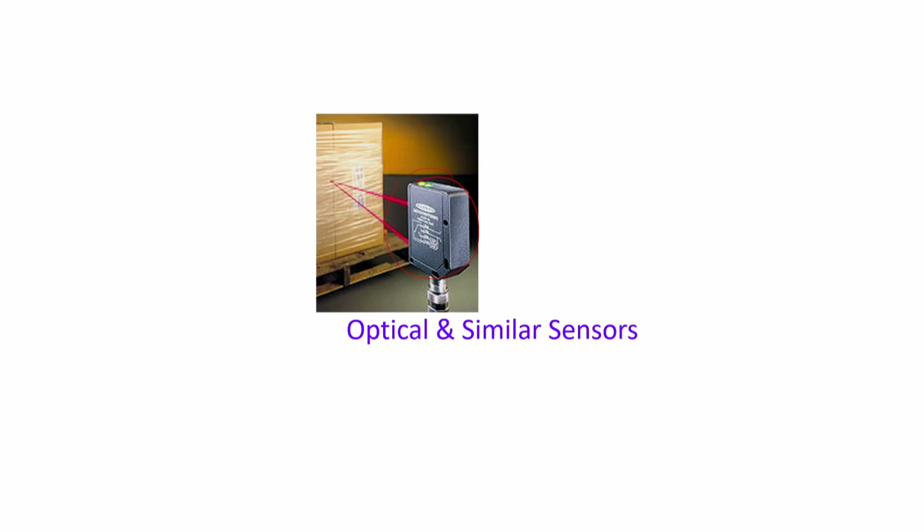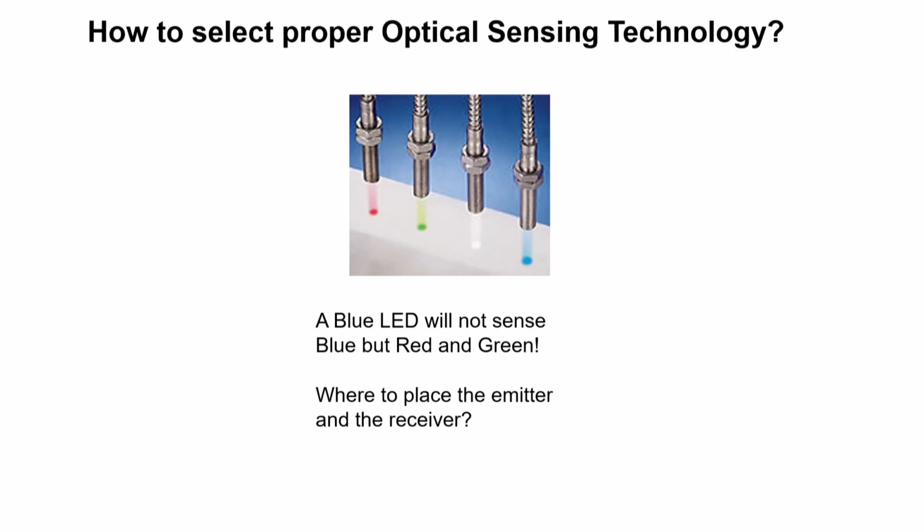Now it can be laser based, it can be LED LDR based, there are many different possibilities with optical sensors, but the fundamental idea is the same: you are sending an optical signal and the signal is reflecting back, and from that reflection you are trying to figure out how far away it is, what the position is, and similar information of the system. And in these directions LEDs are possibly one of the cheapest ways.